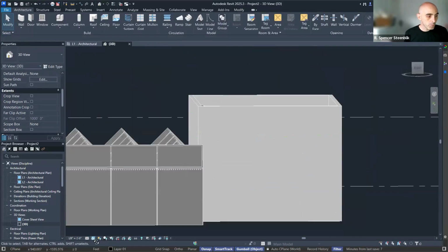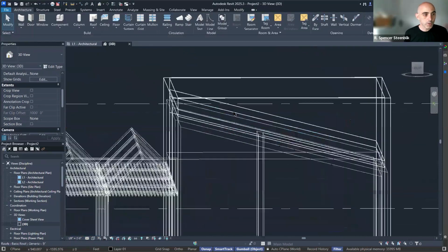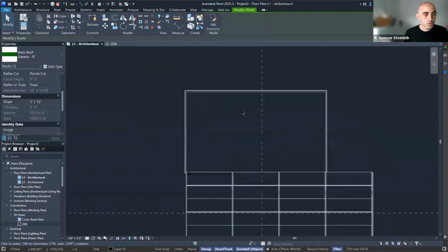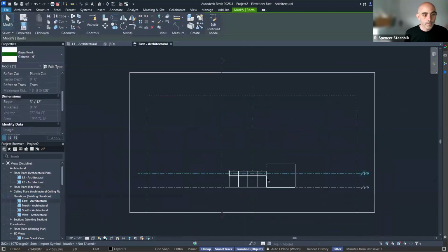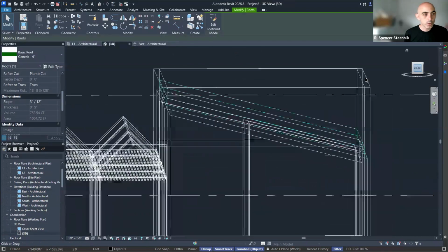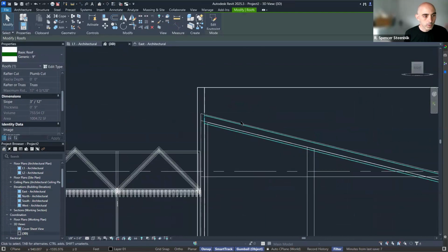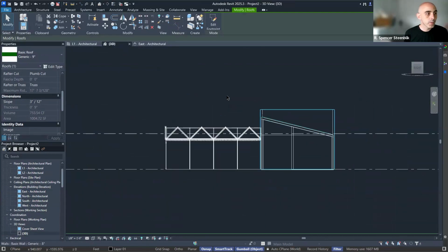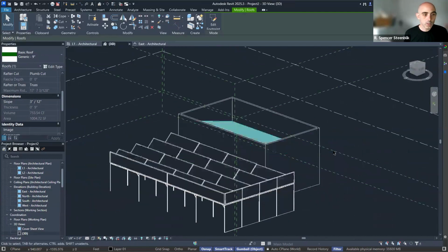So if we go into a wireframe mode here, we should see that being coincidental. And I think I want this to be down a little bit. So I'm going to go into, say, an elevation view. Or not in an elevation view. Let's go back to the 3D view, but go in a right view. Just pull this down. Beautiful. So now we have that. And then what we'll do here, I'm going to get out of this wireframe view, go back to hidden lines.